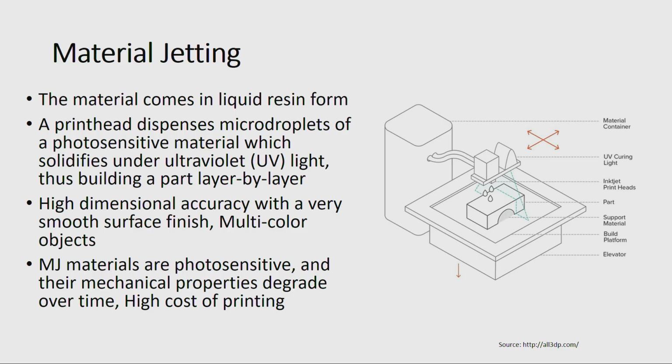The UV light is also attached to the head, then the layer will be cured, and then the printing head will move over this and again deposit ink, and it will be exposed to UV light and cured.